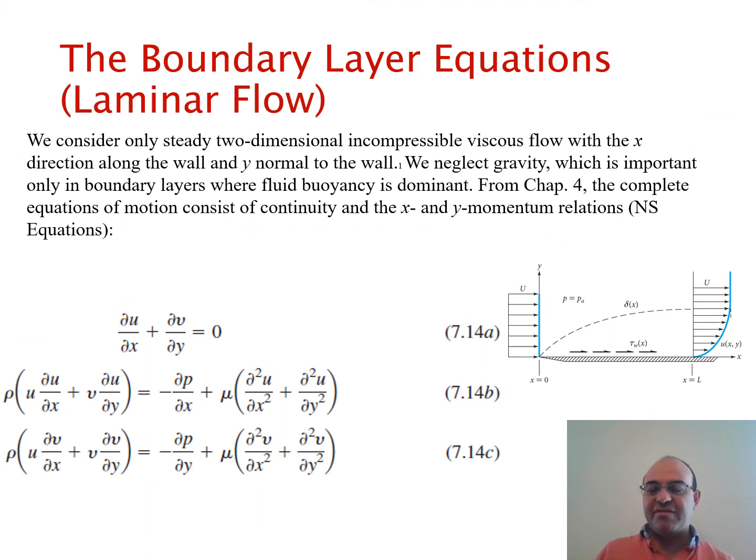Okay, so speaking of details of boundary layer theory, even though we want to be very practical here, I like to show you the equations behind this boundary layer. So we said that in the boundary layer, we do have viscous flow. Outside of it, viscous effects are not present, we call it potential flow, or inviscid flow, or irrotational flow outside of the boundary layer. So let's see what the governing equations are.